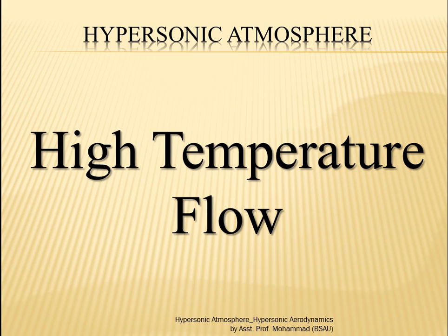So the gas which is flowing with this particular speed can become so hot inside the boundary layer that it can even ionize. So if the surface of the hypersonic vehicle is protected with an ablation material, we know that one of the methods to cool down the surface and protect the structure is ablation heat transfer, in which a volatile material is actually painted above the surface, which starts evaporating at high temperature.